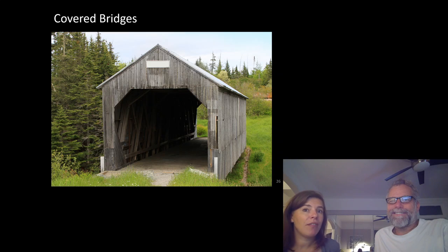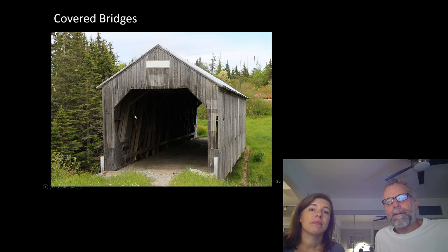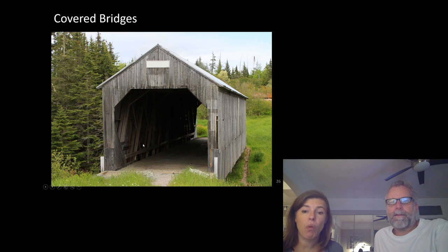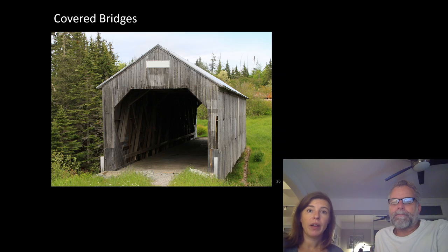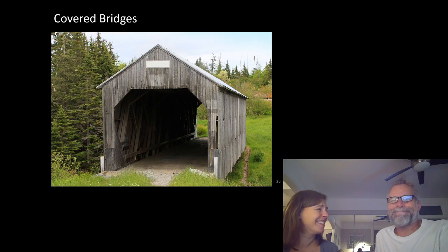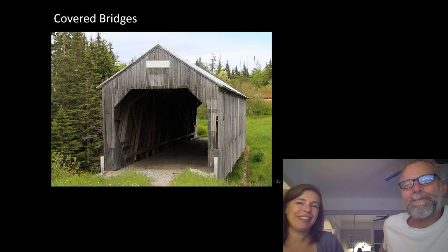It's a question I've always wondered, why bother covering the bridge? Probably when they were building these, a normal bridge wouldn't support snow clearing equipment. My guess is they were building with stick frame elements of wood. To be strong enough, they had to be quite deep. And once you needed it that deep, you needed to brace the top so that the trusses didn't flip over. Then you tied them together, and at that point, might as well cover it. So it's probably some combination of those two things.